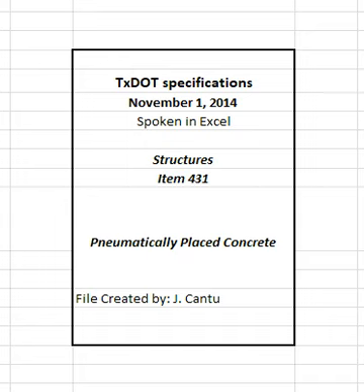2.4 Proportioning and Mixing. Submit for approval a proposed mix design conforming to the basic mix design requirements provided in Table 1 unless otherwise shown on the plans. Table 1. Classes of concrete. See table in specifications. 1 More cement may be used when approved. 2 Higher minimum strengths may be specified. Measure the cement and aggregates by volume and mix with enough water to achieve the desired consistency. Use as little water as possible to achieve sufficient adhesion.